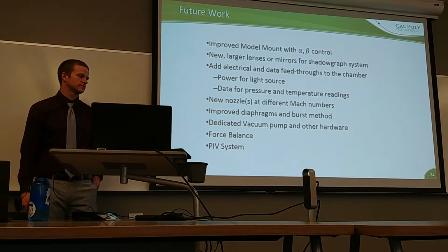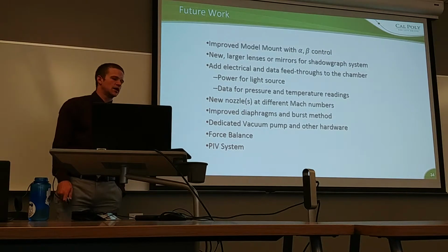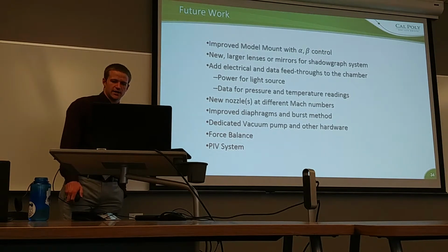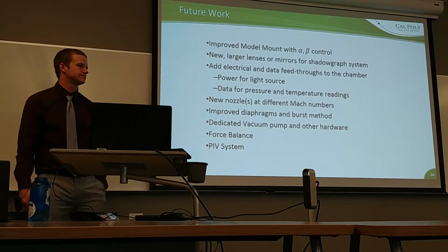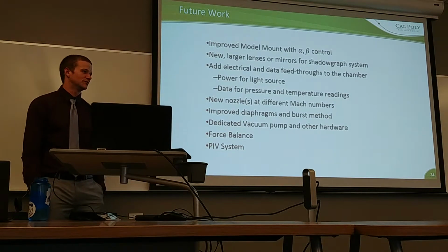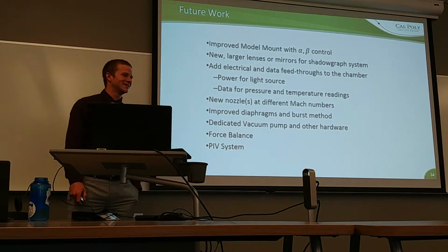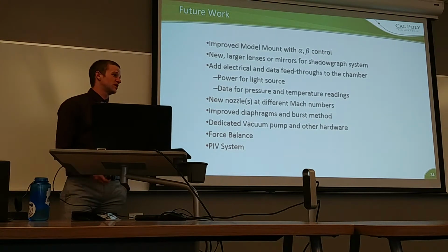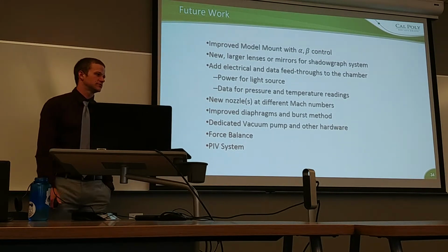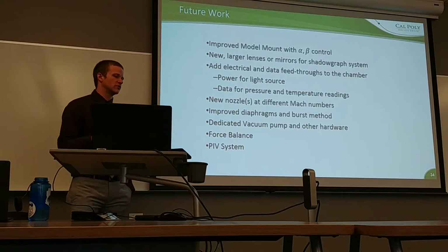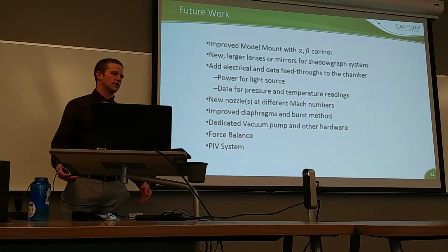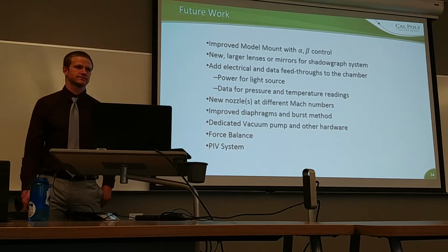Okay, and did you say what pressure that was? I couldn't say off the top of my head. Is that in the thesis? It will be, and if it's not, I'll check. I think it's on the order of 60 torr. This was starting at 25 torr, but it's on the order of 50 to 70 torr when this nozzle would become overexpanded.